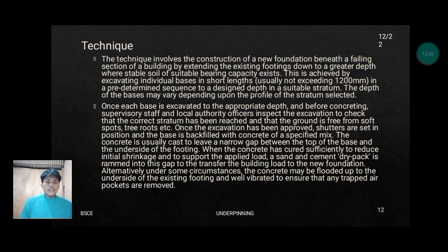Alternatively, under some circumstances, the concrete may be flooded up to the underside of the existing footing and vibrated to ensure that any trapped air pockets are removed.